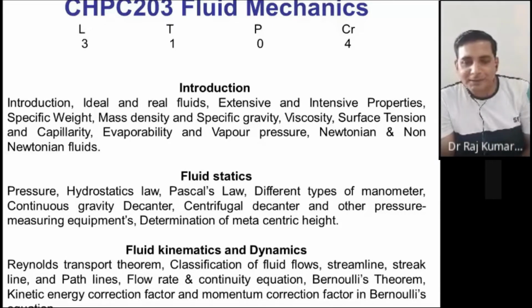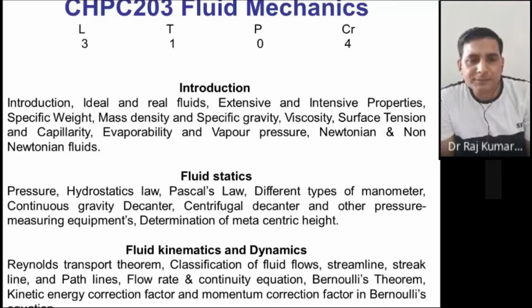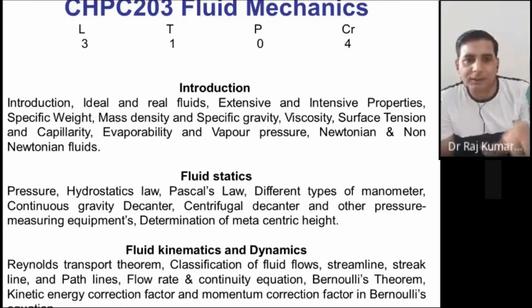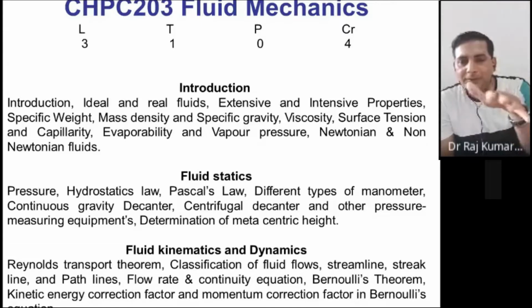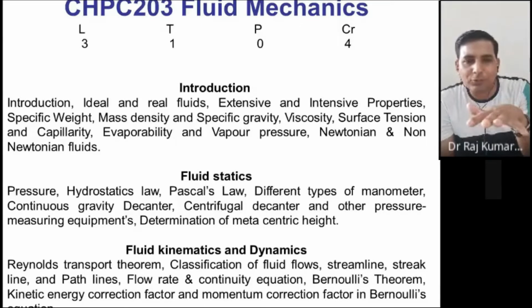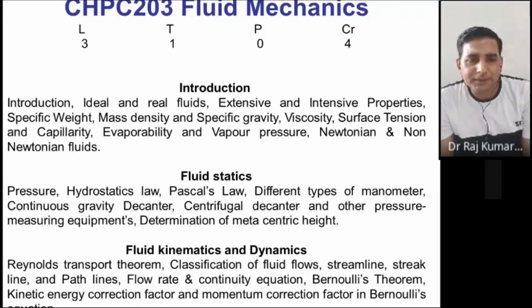If you want to design something like a ship, it should float with some submerged part. So you have a metacentric height. The stability part is so that in case of a slight tilt in the waves of the sea, your boat or ship should not topple down, right? So that is one thing.